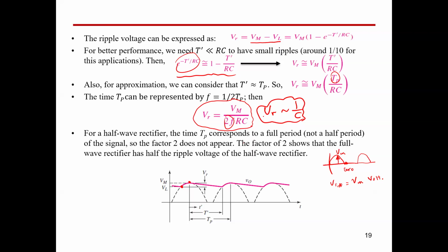So we can say, guys, V ripple is inversely proportional to capacitance. If you would like to reduce the ripple voltage of your rectifier, and this is appreciated and recommended, we can increase the capacitance value. But for sure, guys, every design has some limits or thresholds.